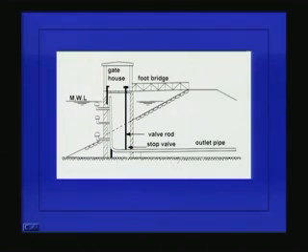We have another type of intake structure. This is what we call a dry well intake structure or dry intake. It's dry intake because the water is never stored in this intake structure itself. I have this outlet pipe here which is coming, and then entry into this outlet pipe is through this vertical riser, and there are multiple entries into this vertical riser which take water from the reservoir.